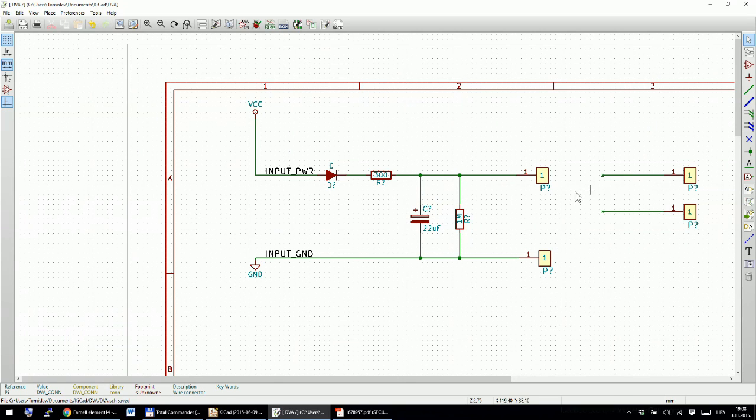So the easiest way to connect these two now is just to copy your net name with the letter C and place it on this piece of wire. I will copy another one. And that's it. So these two lines, this one and this one, are virtually connected, and when you draw your PCB, those will get connected automatically by Kicad.